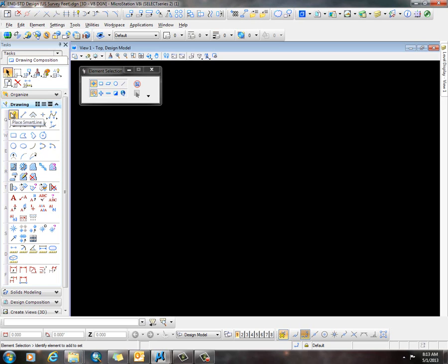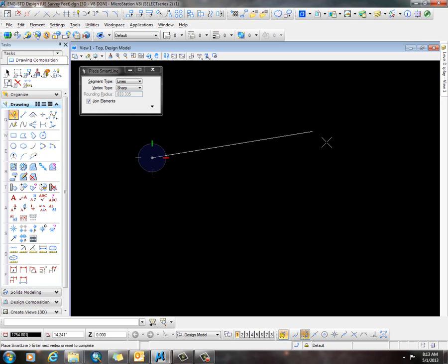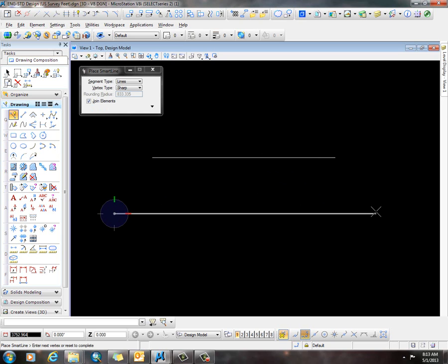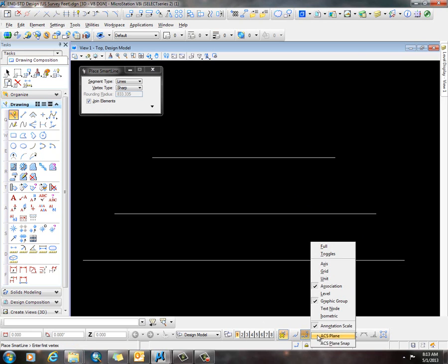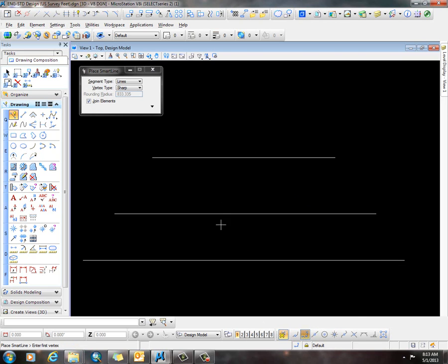The Civ Tools toolbar is basically only used to set elevations of elements. The previous tutorial made you ensure that your depth lock was on, but let's say you've created a grading plan and you need to create a surface for volumes and so forth, then you will want to set the individual contour line elevations.